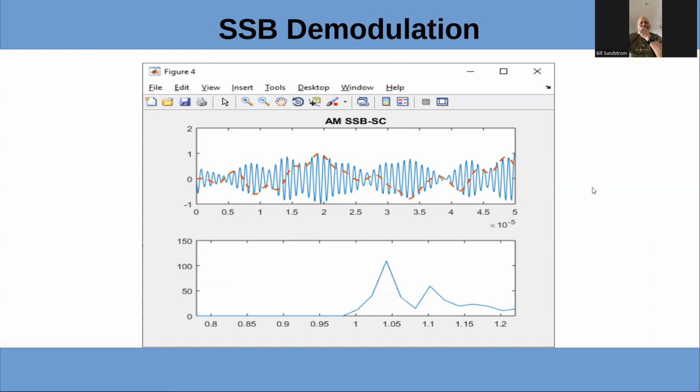All right. So this one gained a lot of advantage with sideband because effective power is much higher because the bandwidth is narrower. I think this one is trying to show kind of what the waveform for a single sideband signal looks like. I haven't had much luck in actually finding what I think is a decent one, probably because it's very hard to capture since there's no reference. There's no carrier to lock on if you want to look at it with an oscilloscope.